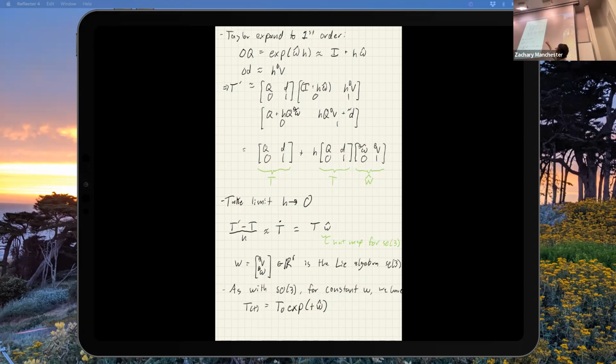So it turns out you can write down the foot position in the body frame in there as a new vector, and it still obeys the group transformation properties. You can start writing down sensor biases, like your gyro bias in the body frame. You can stuff that in there too. So all these new things, you can keep stuffing into this group and make a bigger and bigger matrix, and it still maintains this group symmetry property. So you can write down invariant Kalman filters for some pretty interesting things. Cool stuff, useful in robotics. You get provable exponential convergence for your nonlinear system in your extended Kalman filter, which is slick.